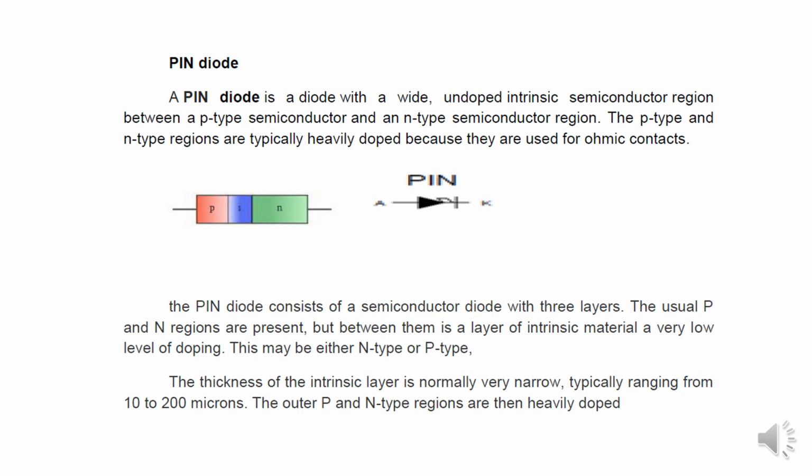Here the very heavily doped region between the n and p type, or wide n region, makes an inefficient rectifier, and at zero or reverse bias the pin junction has low capacitance, so there is high resistance to RF signal. The pin diode also has heavily doped p-type and n-type regions separated by an intrinsic region. When reverse biased, it acts as an almost constant capacitance, and when forward biased, it behaves as a variable resistor.